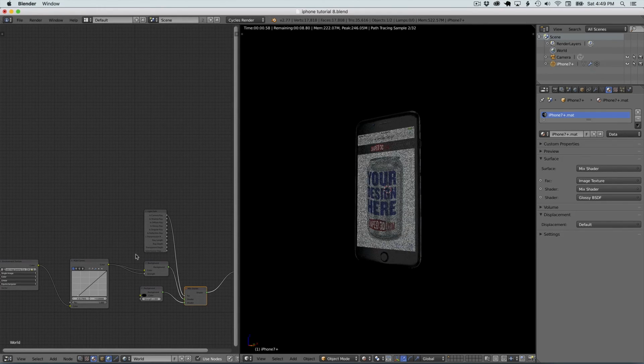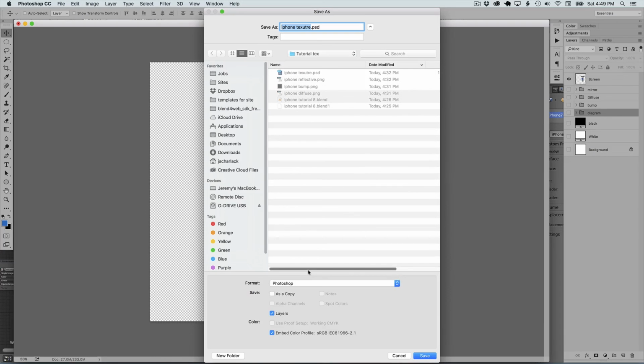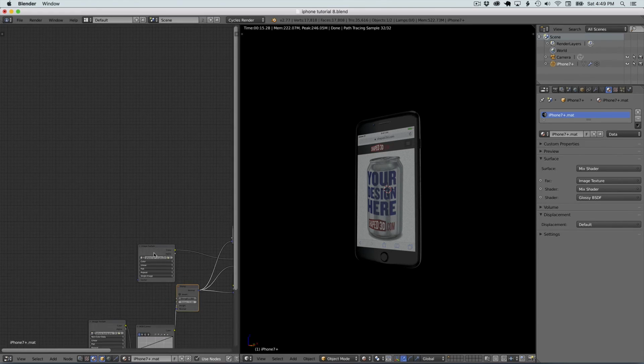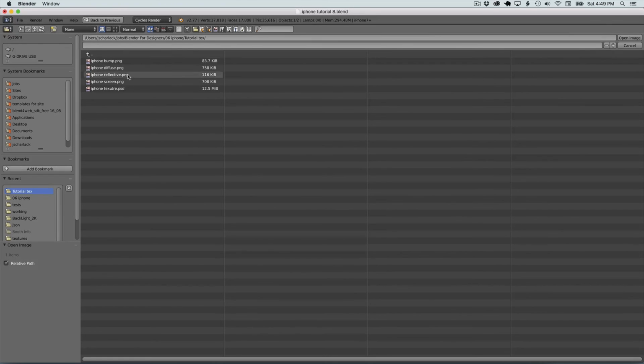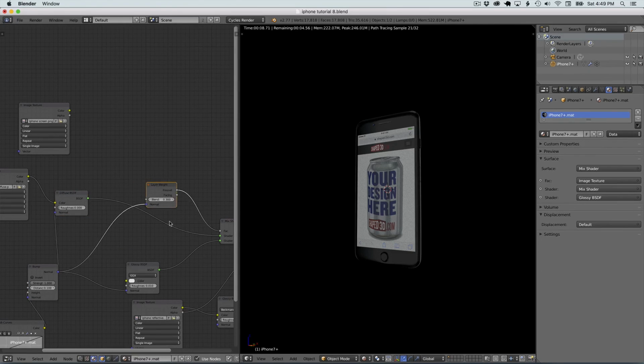All right, the screen is not overly glossy like this. It's actually illuminated, so we want to capture that. Let's go back to our document here, and we're just going to do one of just the screen, and go back to the material and add the screen. We're going to add that before, like with the diffuse, because you want to mix the glossy in there. So we're going to add a mix shader in here.